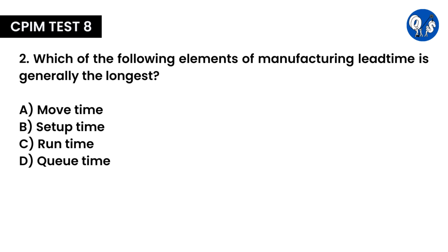Generally only 10 to 20% of manufacturing lead time is actual operation time. The rest of the time is caused by work in process time when the part is not being worked on. Of this stagnant time, queue time accounts for the longest time.